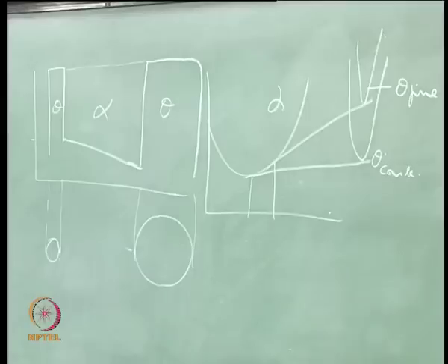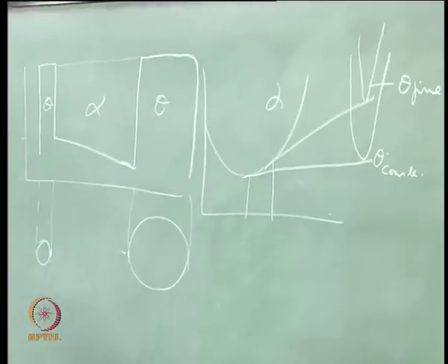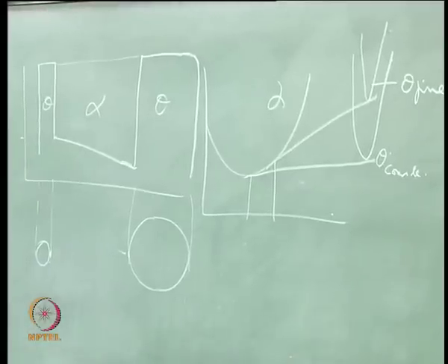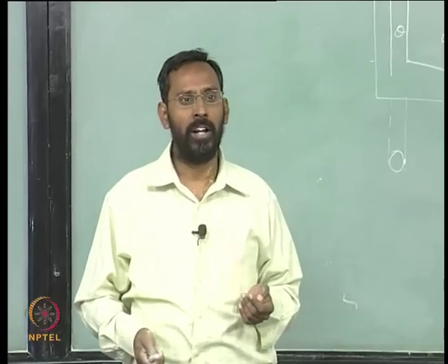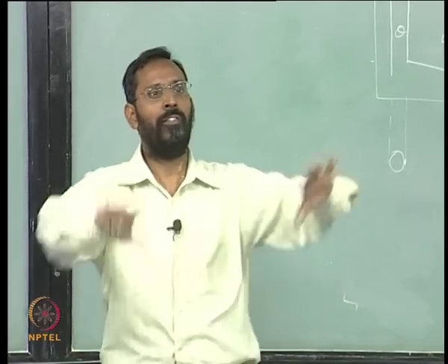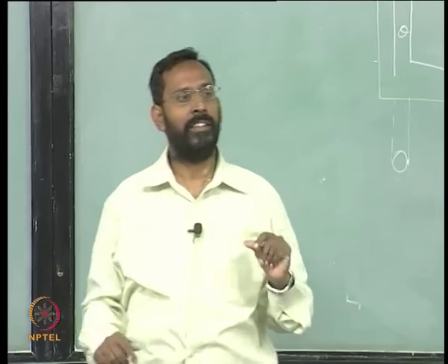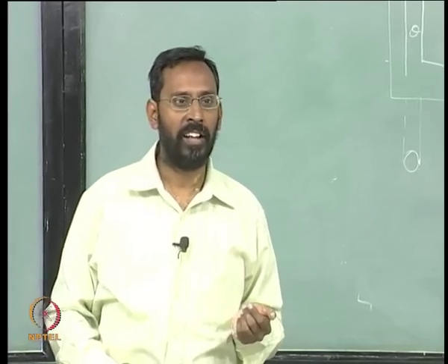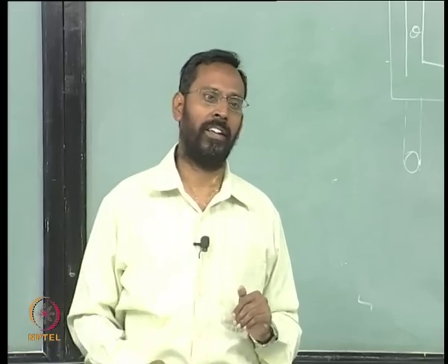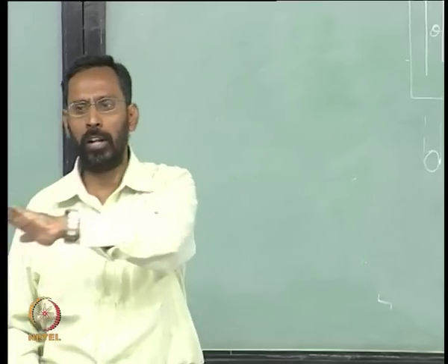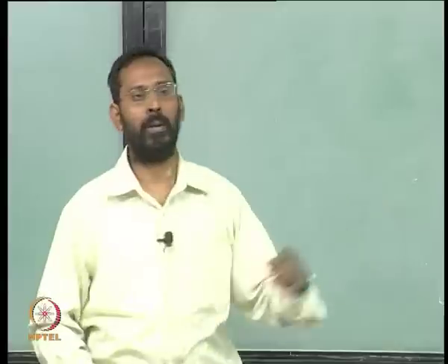Okay, dissolution of one precipitate and growth of another precipitate is not possible. The only thing is, ideally, if all precipitation has occurred at the same time, and if it is a homogeneous precipitation, not a heterogeneous precipitation, then in principle nuclei have formed everywhere. This is what we call a site saturation case, where there is no more nucleation taking place. At time t equal to 0, all the nucleation has taken place and all of them are trying to grow. When they are trying to grow, you get into this problem.